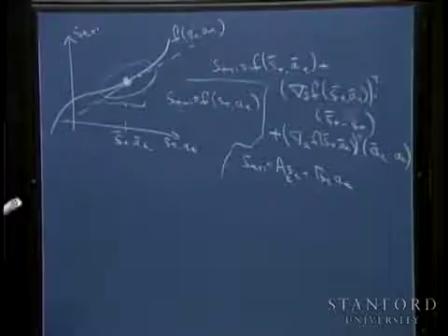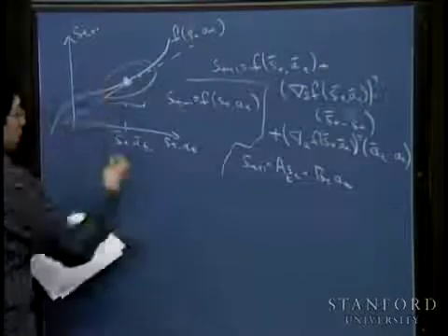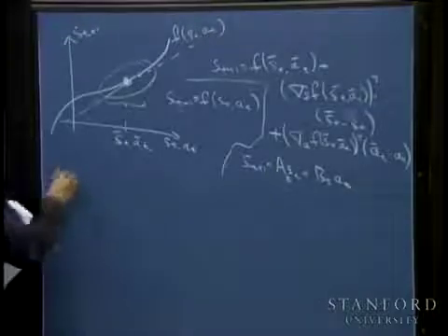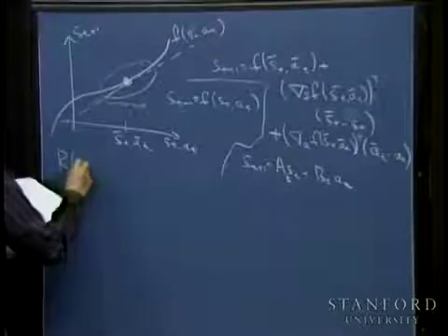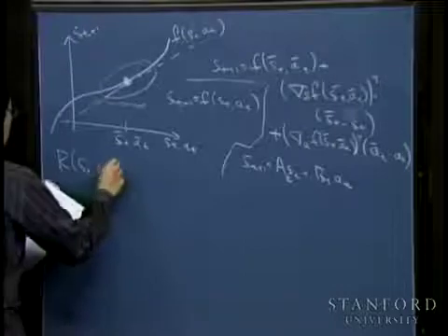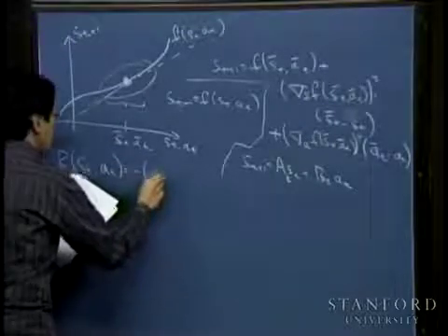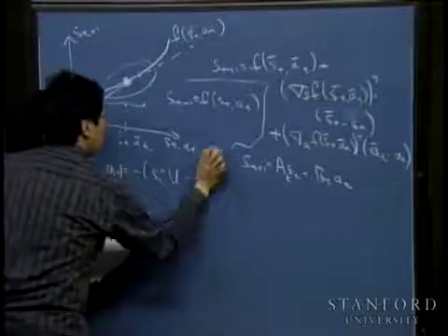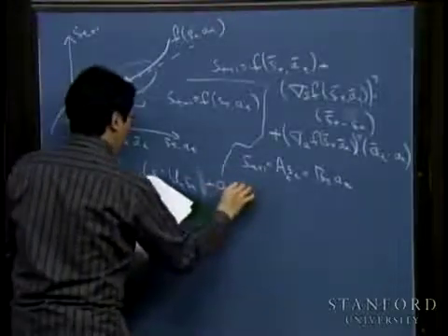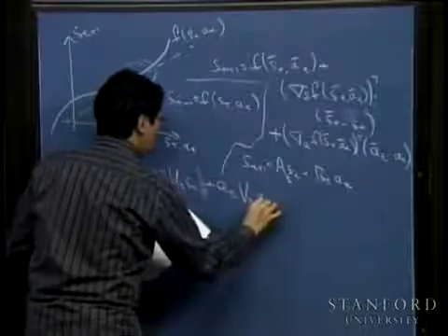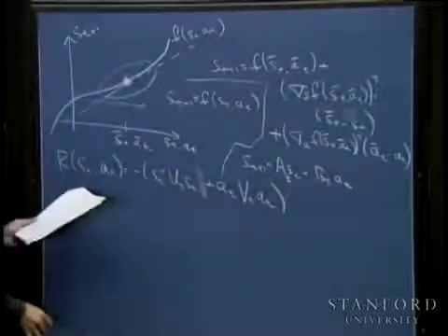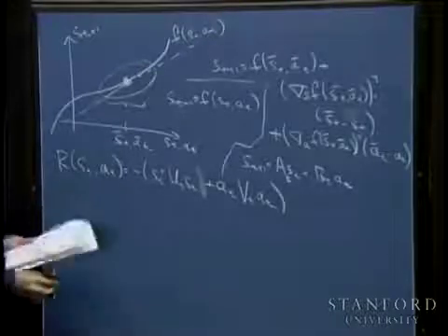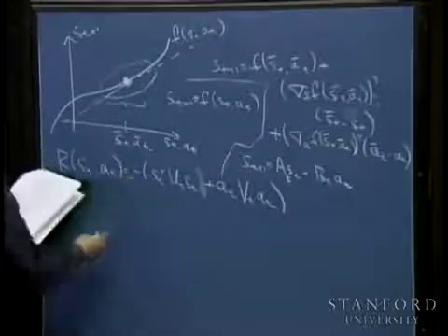Right. So, okay, this is how you might come up with a linear model. And if you do that, then for LQR, we also had this sort of quadratic reward function, where the matrices U_t and V_t are positive semi-definite, so the rewards are always negative, because of this minus sign.